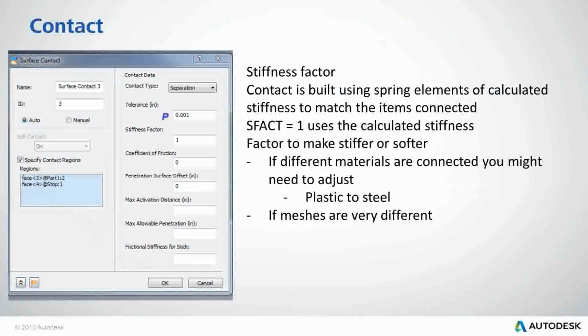Today's topic is setting up contact in the In-CAD environment. In-CAD is available for Autodesk Inventor and SolidWorks. It is basically a user interface for our Nastran solver. You can have a part or an assembly that you open in Inventor or SolidWorks, then access the In-CAD environment where you set up the finite element analysis and run it using the Nastran solvers.